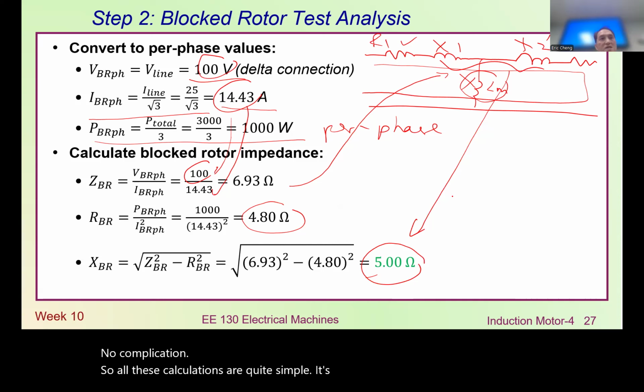We also conduct some measurement at 0.8 ohm per phase, using an ohmmeter. Because we use an ohmmeter, the temperature is usually only room temperature, say 25 degrees C. And then the operation temperature, why do we have that? Because under the short circuit test, the motor gets very hot because we are locking the motor. So we energize it with some voltage, the motor winding gets very hot, and the temperature usually goes up. Say for this case, it goes up to 75 degrees C.